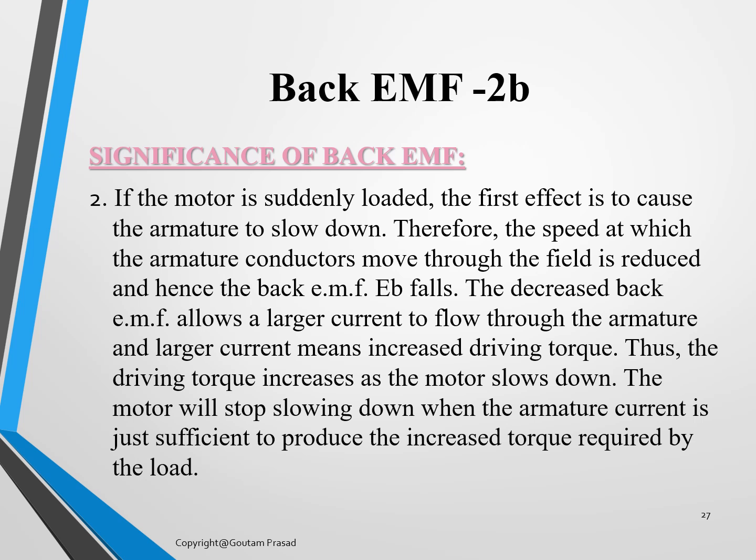Because the speed has reduced, the cutting of the flux by the conductors will also reduce, and that will reduce the back EMF in the conductors. So this decreased back EMF allows a larger current to flow through the armature.